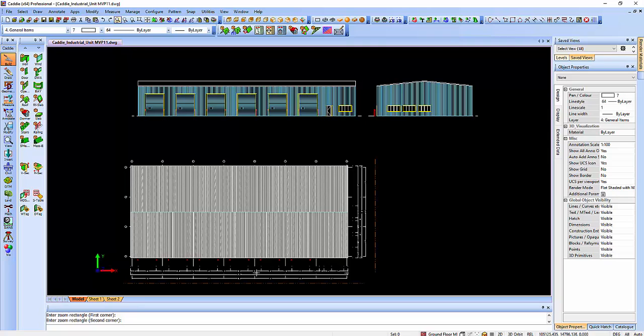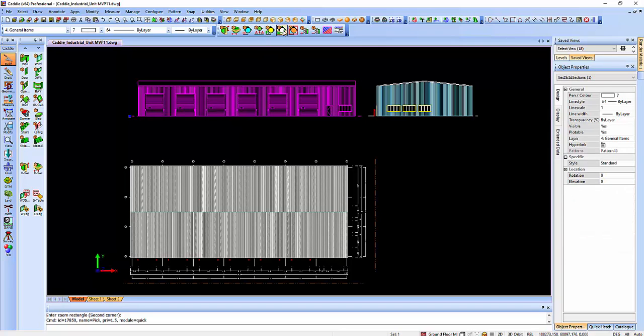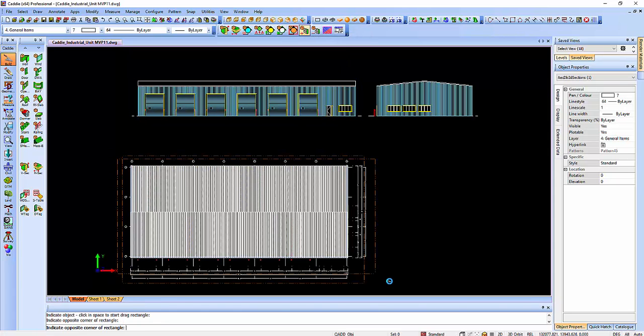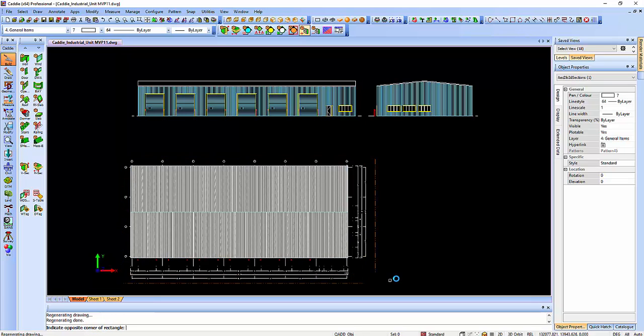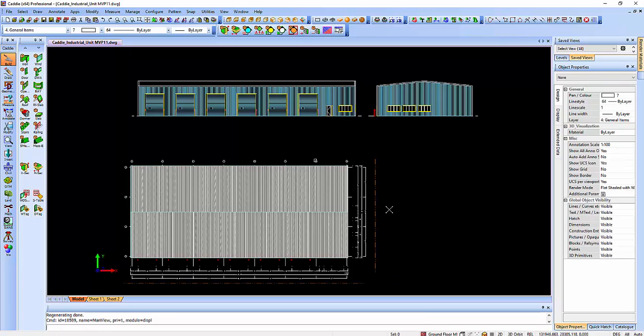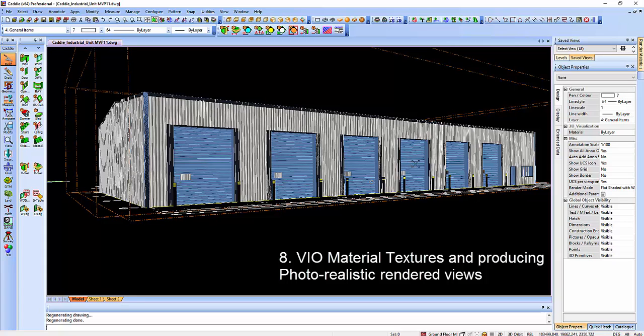Now to introduce the trim panels onto our elevations, we just simply select the section and then say add to all sections. Those other objects I can just drag over the whole of the building, and it will just automatically add those to it. So having generated our plan and elevations, we can now look to our 3D model. Roller shutter doors, bollards, and so on.